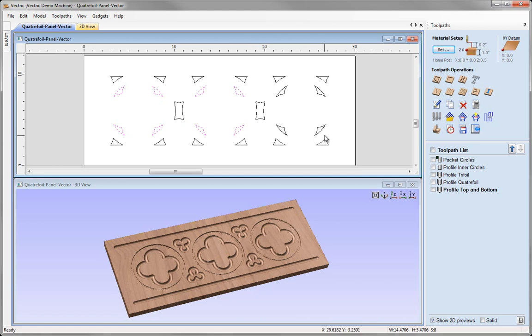If I drag from the right upwards, then it's going to select any item that I touch, so it doesn't need to be completely enclosed, it just needs to fall partly within the selection box. So if I click here and drag up to the left, then I don't need to completely enclose these, I just need to partially touch them. I can let go and they'll be added to that selection as well.